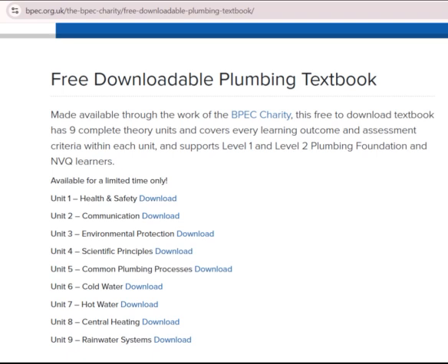Temperature control was maintained by using a room thermostat to control the heating and a cylinder thermostat to control the secondary hot water. Three initial systems were developed: A. The Honeywell Y-Plan using a 3-port motorized mid-position valve. B. The Honeywell W-Plan using a 3-port motorized diverter valve, and C. The Honeywell S-Plan using 2-port motorized zone valves.